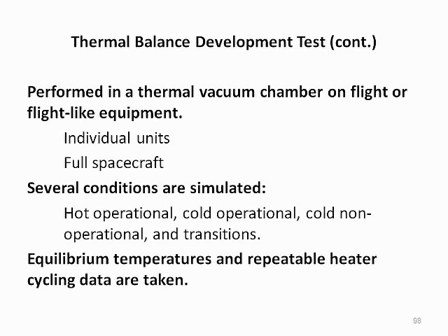Hot operating, cold non-operating, and sometimes hot non-operating steady-state conditions may be simulated, along with transitions between temperature levels, to provide the data needed to evaluate design performance and check thermal math models. Equilibrium temperatures and repeatable heater cycling data are recorded for both the test article and boundary conditions.